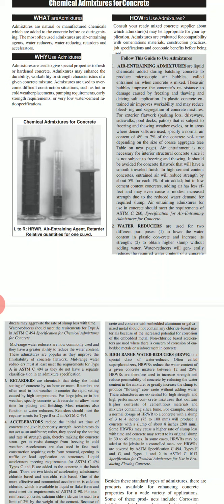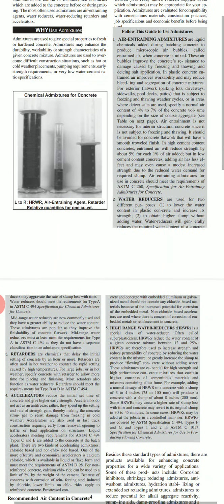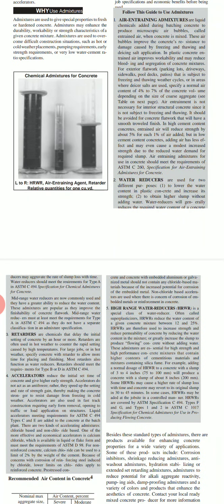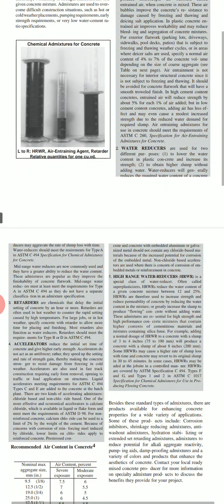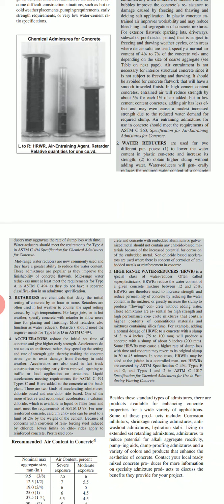The water reducer will generally reduce the required water content of a concrete. Water reducers may accelerate the rate of slump loss with time. Water reducers should meet the requirements of ASTM C494 specification for chemical admixtures for concrete. Okay, these ASTM standards have to match.